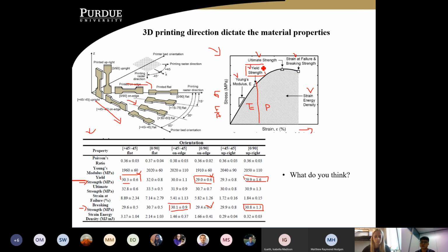The reason why I'm talking about this is that I'm trying to save you guys time in designing, because if you already know that the load you're applying already surpasses the yield strength, then at the first point of design, you shouldn't even choose that material for your items, right? So that's something I would like you guys to take away from at least this 15-minute skill session. Now, moving forward, there's also a lot of students who talk about fatigue.